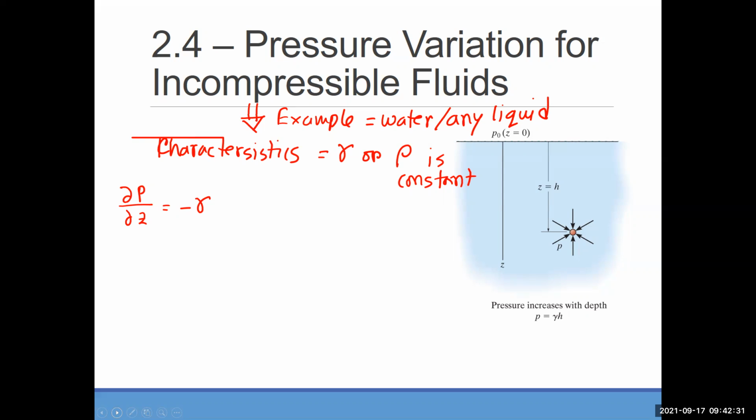Okay, so that is the equation, right? The pressure variation in vertical direction. Now, when we develop that equation, can you tell me in which direction we consider z as positive? Upper direction? That is the usual norm, right? But here, at the surface of any liquid, since it's open to atmosphere, the gauge pressure is what? Yes. So gauge pressure is 0 at the surface.